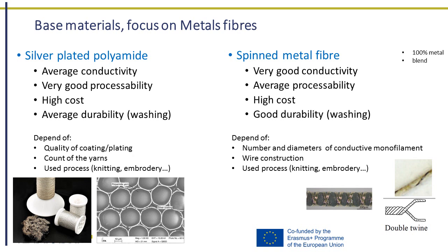Again, these outlines are dependent on some parameters. We could cite the number and the diameter of conductive monofilaments, which will influence the conductivity. The wire construction will also impact the cost, the conductivity, and the durability. Unlike the silver plated polyamide, the global quality and durability of the final product will be dependent on the process.